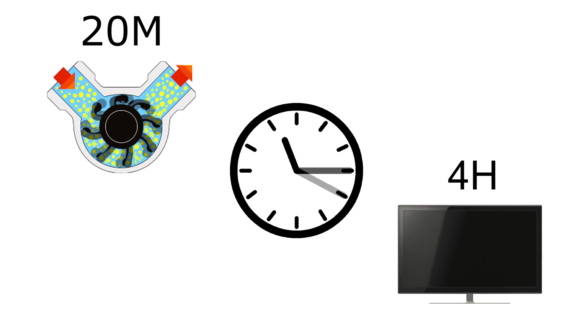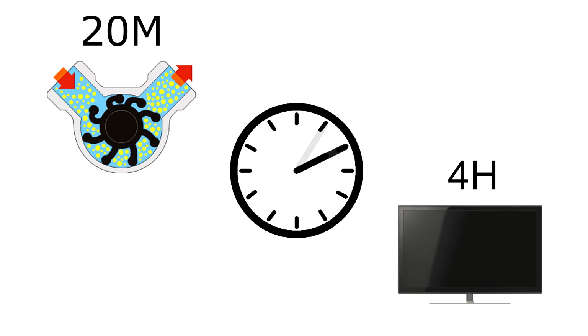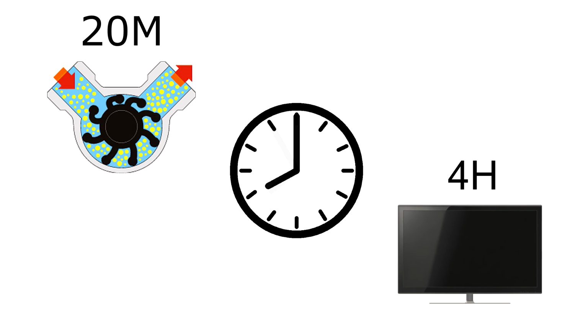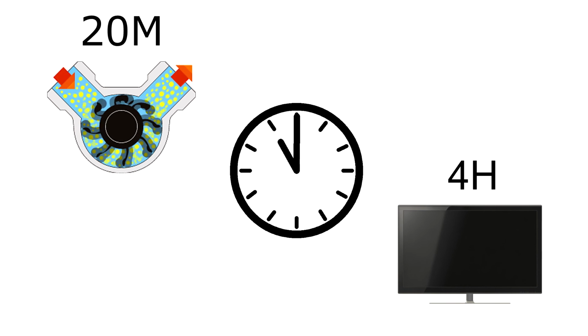For example, how long would you expect to watch your television at night? Note that this calculator only considers your total required wattage, so if you plan to run different devices for different amounts of time, run the calculator for each device separately. For example, if you have a water pump that only turns on a few times a day for a few minutes at a time, you wouldn't want to include that in the total wattage, or the calculator will think that the pump is running for the same amount of time as everything else is.